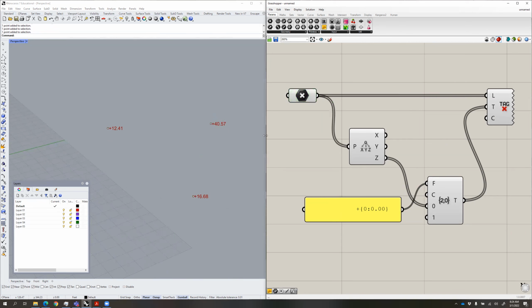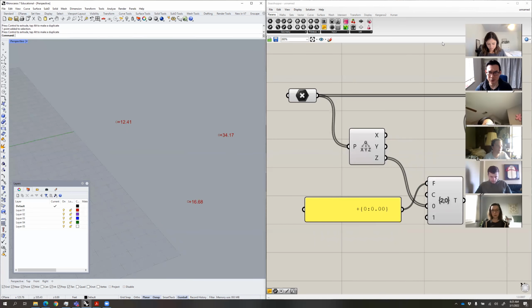And as long as you set those points in here, like I did here, you can do that. And now you can work on your design, create your plans, create your walks, and you always know at all times, all right, I'm doing something at that spot elevation, that spot elevation, that spot elevation, and if you move things around, they adjust as we go. All right, congratulations, you just wrote your first Grasshopper script if you've been following along. Any questions?